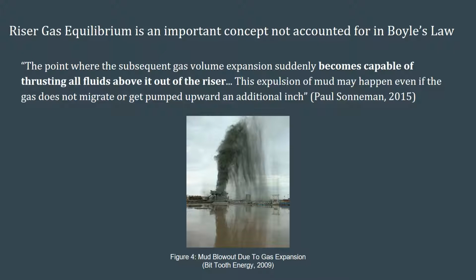An important concept that's not included in Boyle's law is riser gas equilibrium, which is the point where the subsequent gas volume expansion suddenly becomes capable of thrusting all fluids above it out of the riser. This expulsion of mud may happen even if the gas does not migrate or get pumped upward an additional inch. Since this is not included in Boyle's law, there's no way that Boyle's law will be able to model the expansion of gas accurately.